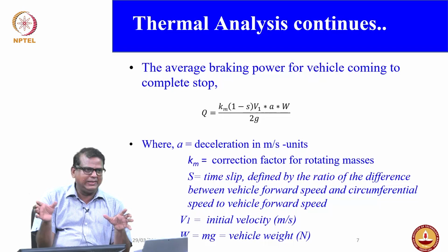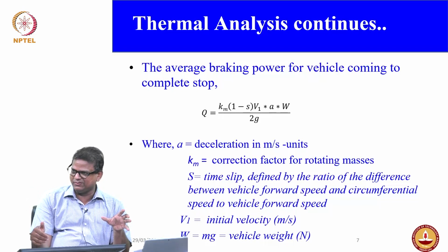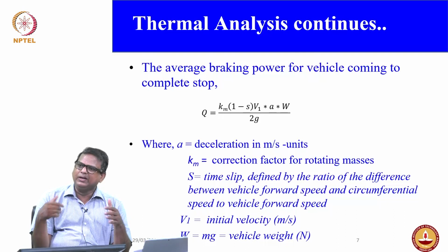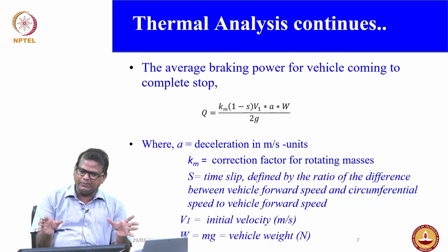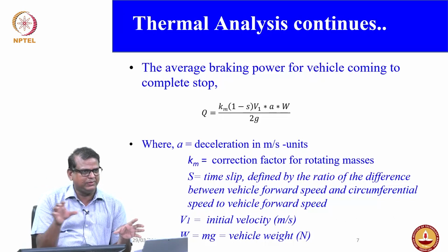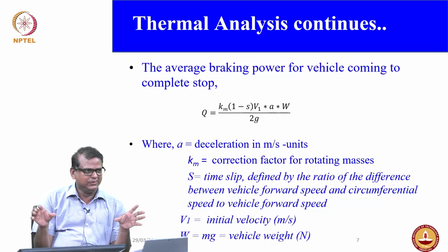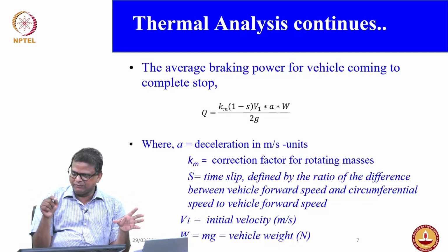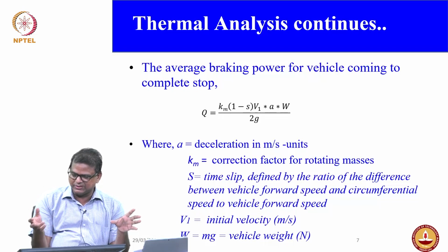That is called negative slip. 4% is reduced. That's negative slip. Instead of 100 RPM, if the output gear rotates at 104 RPM, the difference is 4 RPM. That is the slip, which is 4%, a positive slip. Both ways are there, positive slip and negative slip.